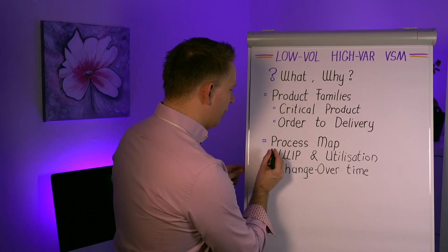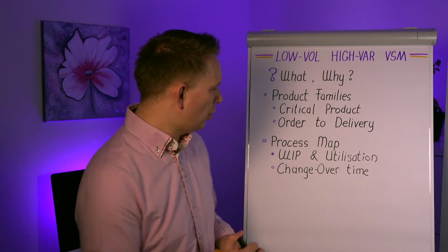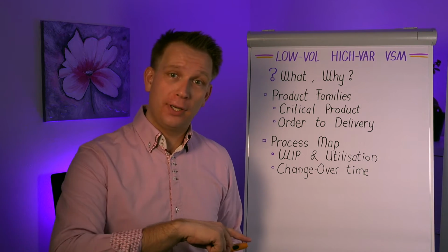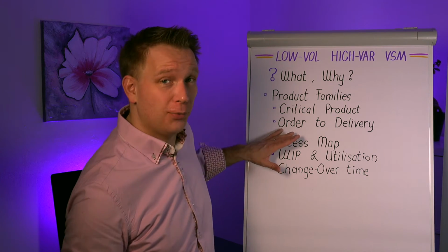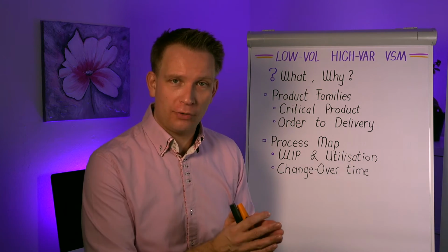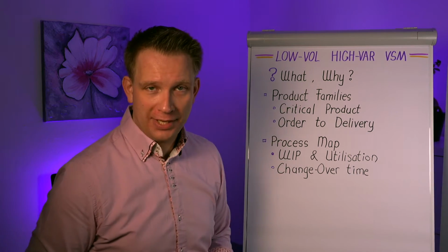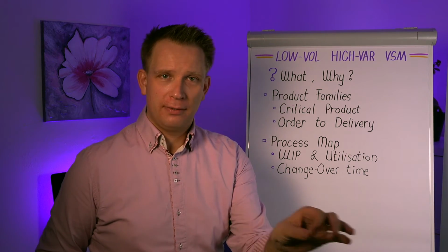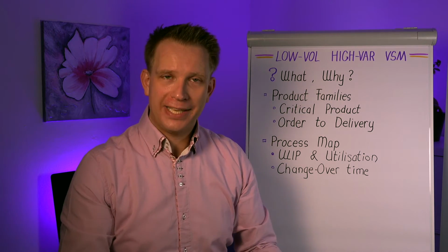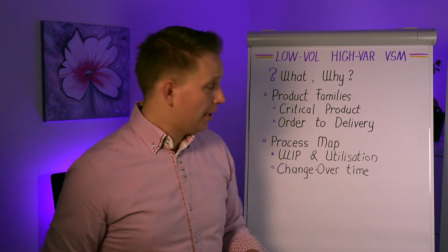And that is based on really counting all of the stocks, all of that inventory you have as work in process. Not just for the product you are now following, because you're not really following a product, but how much inventory, how much work in progress is waiting for a specific part of your production process. So count all the different orders that are now ready to take this machine as the next step. And you do that for all of the machines and processes in your layout.